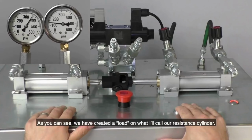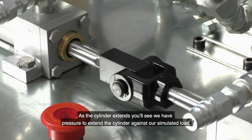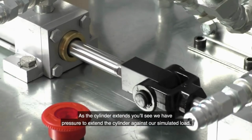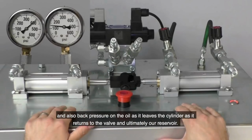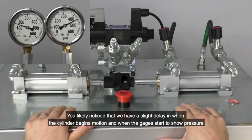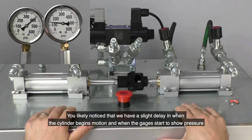As you can see, we have created a load on what I'll call our resistance cylinder. As the cylinder extends, you'll see we have pressure to extend the cylinder against our simulated load and also back pressure as the oil leaves the cylinder and returns ultimately to our reservoir. You likely have noticed that we have a slight delay between when the cylinder begins motion and when the gauge starts to show pressure.